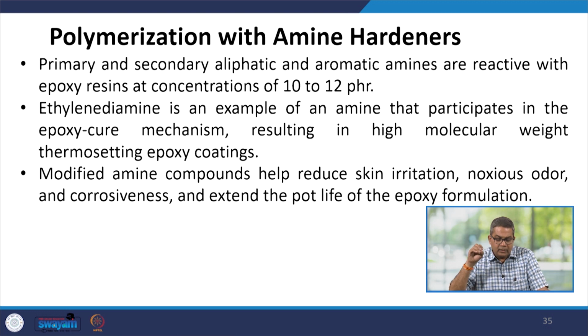Ethylene diamine is an example of an amine that participates in the epoxy cure mechanism, resulting in high molecular weight thermosetting epoxy coating. Modified amine compounds help reduce skin irritation, noxious odor and corrosiveness, and they extend the pot life of epoxy formulation.